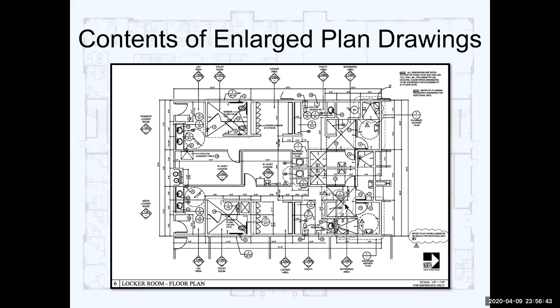Here we have an area that's been X'd out for flow. This is a floor drain, so we're indicating with these arrows here and here and here that we want all the water to be shed to the floor drain and not have an opportunity to spread out beyond those areas. But by putting that graphic representation of slope and where the slope breaks, we end up with small inconsistencies dimensioning. We just have to go back through and make sure that it's not going through the number, or that if we're doing it, we're trying to isolate it from other graphic conflicts.